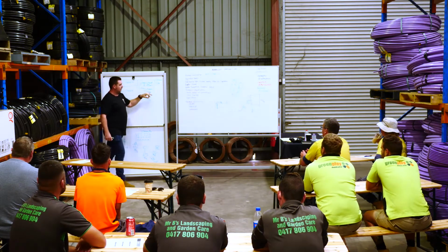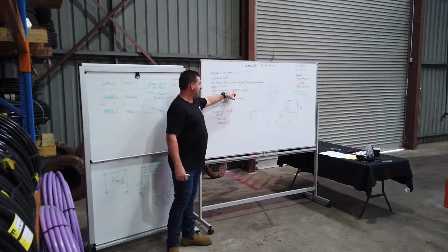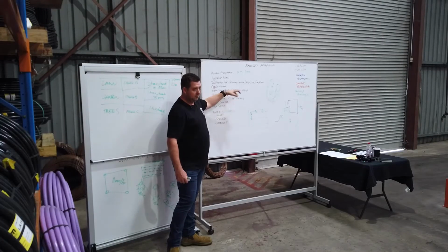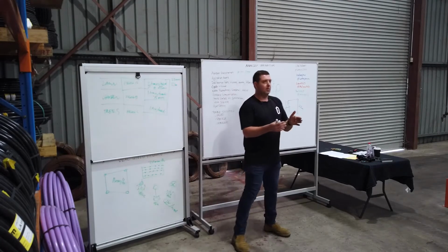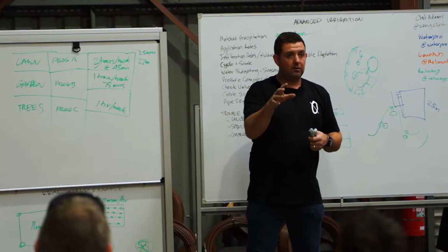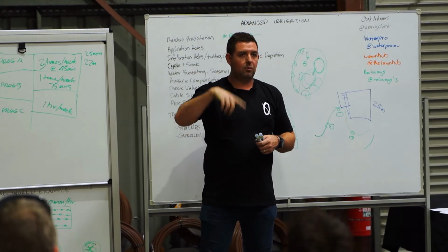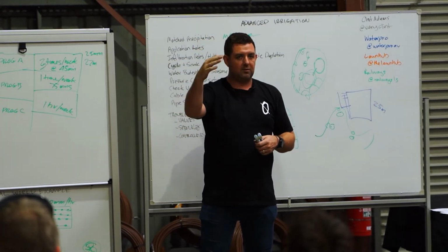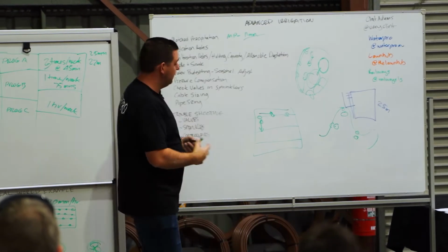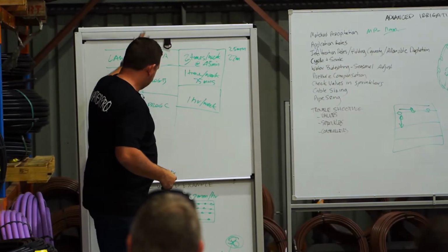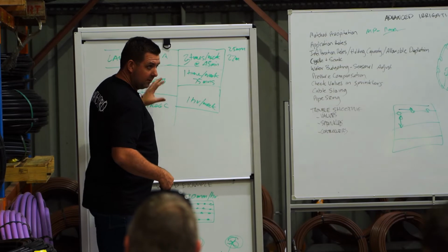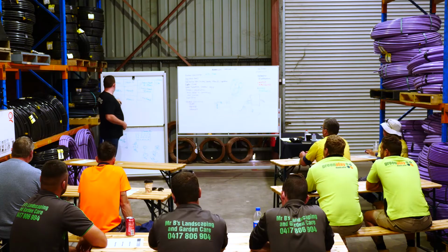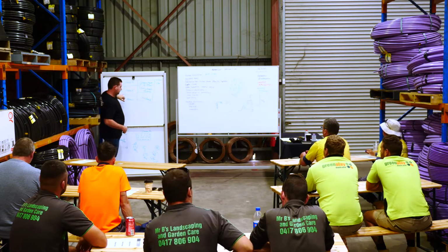So that can either occur using seasonal adjust, which is an automatic change in the controller, or if you're going back to the non-Wi-Fi controllers, you can go into the seasonal adjust function and just press it up to 120 or 140%, or down to 80, 70 or 60% in winter, and these times will move up and down. Yeah? So that's water budgeting and seasonal adjust.